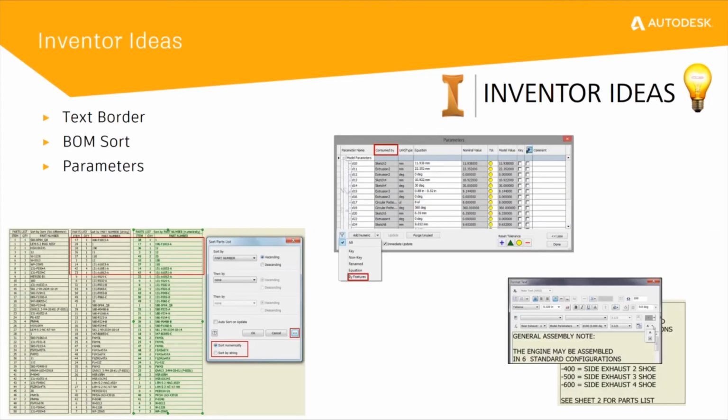We've done a lot of things with the parameter dialog. So now there's this consumed by column. As you select features in the screen, it'll switch to just the parameters that are relevant to that particular feature. There's also a quick pick filter at the bottom where you can say by feature and look at parameters for specific features, which is really great as you start looking at very complex assembly or part designs.